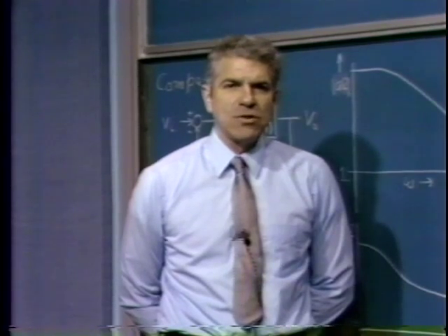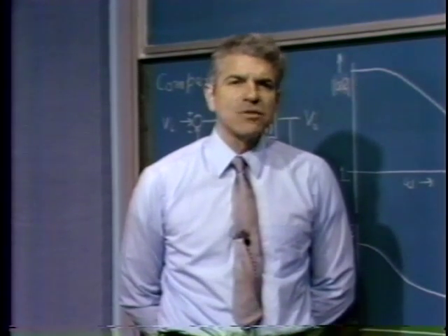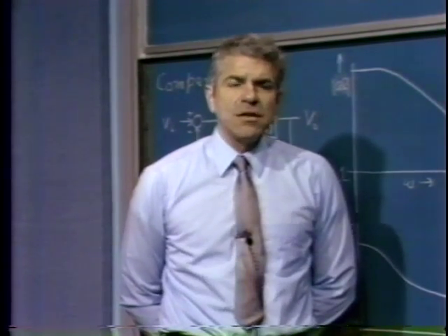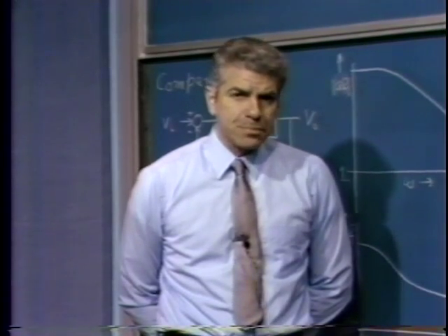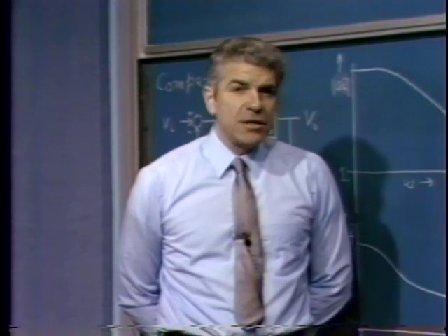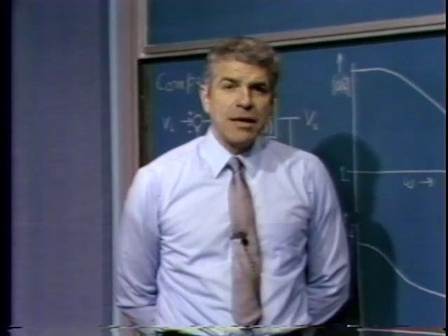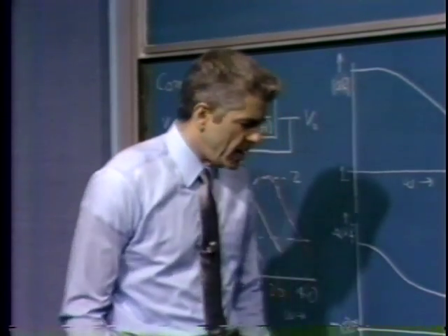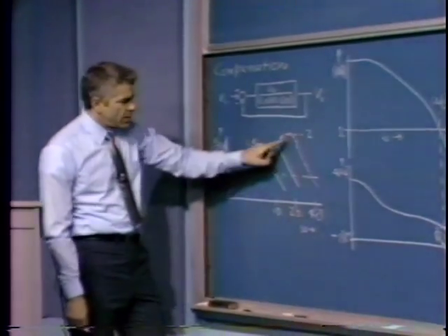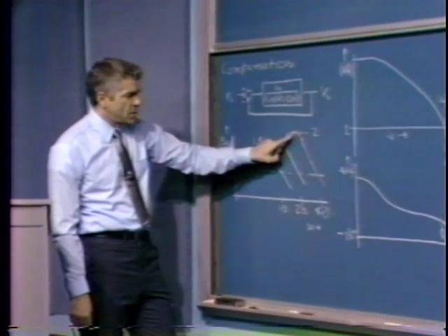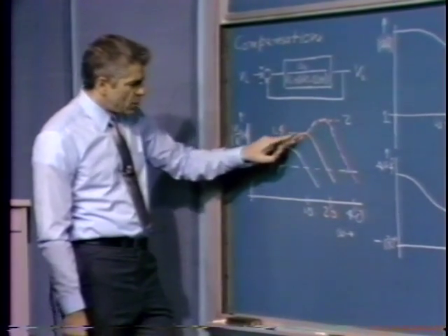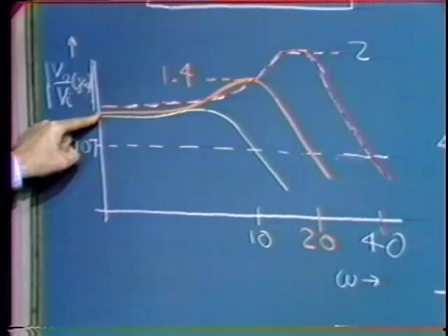But if we have a gain margin of 3 and are sure we'll maintain it, it has relatively little influence on the stability, the relative stability of the system. The big indicator of relative stability is the phase margin. And in fact, there is a very good relationship between phase margin and a quantity that we might define as M sub p. M sub p is a frequency domain concept, and in fact M sub p is the ratio of the maximum resonant peak that we get for a system in our standard form with unity feedback, the maximum peak we get divided by the low frequency magnitude of the closed loop gain.